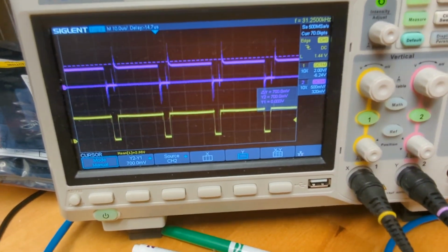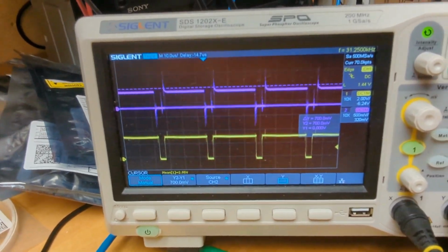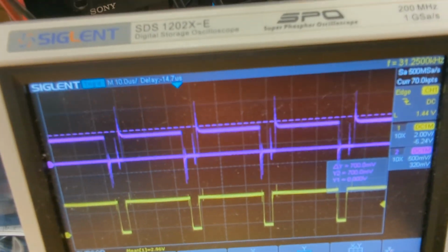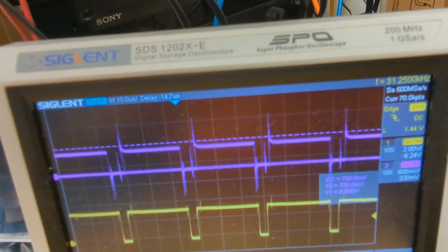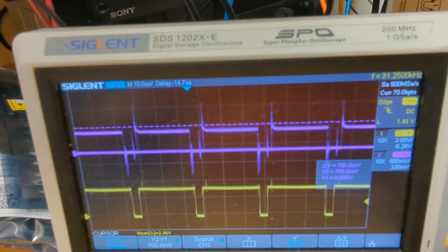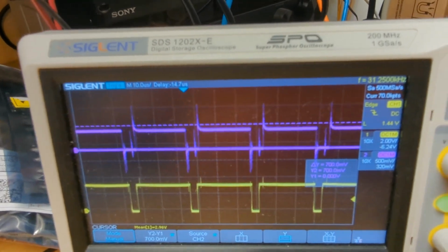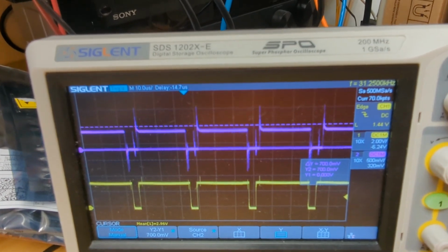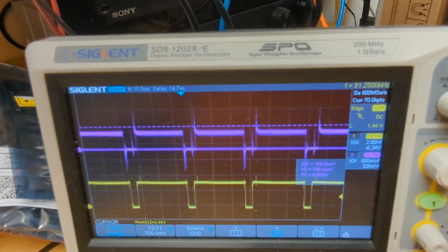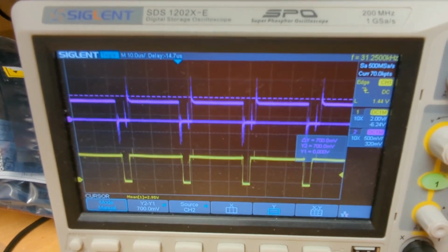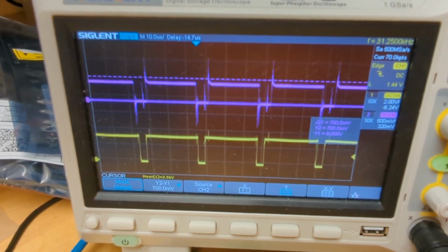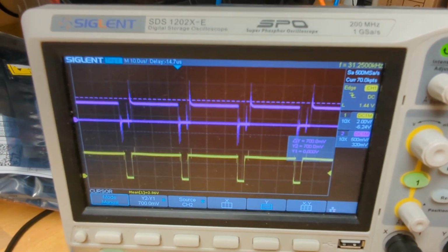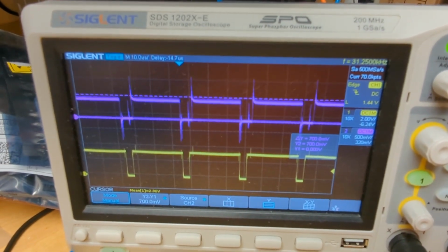Here's what my scope says is going on right now. You can see a huge amount of overshoot on that top purple trace, which is clipped onto the red video signal. If I move the resistors around on my crappy breadboard here, you can really see that thing glitching around. That's because when it bounces around, it's making and breaking contact with the video monitor, and the signal is not being terminated when I do that.